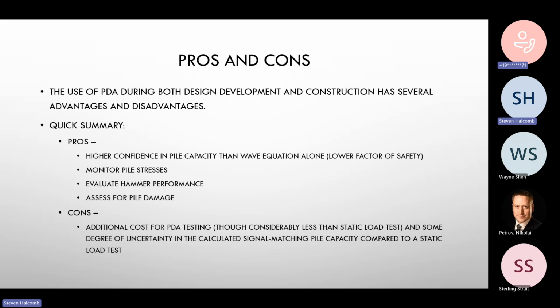I guess the PDA, when it's used, it's usually because it's the most effective tool you have to solve whatever problem you're trying to solve at the time. And so it's kind of difficult to talk about the cons of it. There certainly are things you need to worry about. You need to get a professional on site who knows how to do it, and you might need to wait for them to be available. You're going to have to accommodate them by getting power or maybe a lift to the site so they can drill and tap to install the instruments.